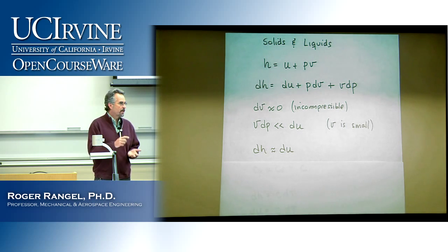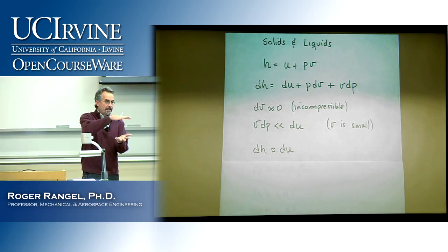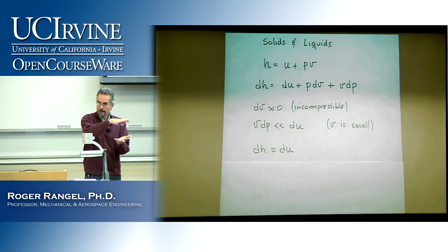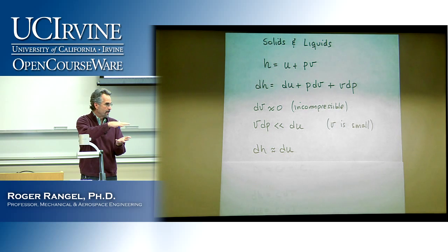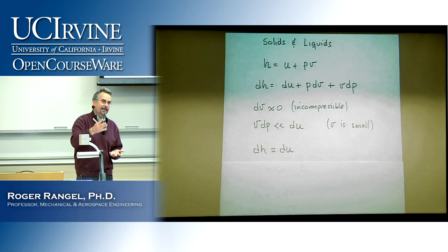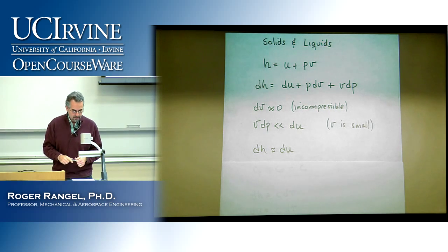That makes sense because if it is a liquid, remember, it's not turning into vapor, and I put it in the cylinder with the piston moving, and I'm just raising the temperature by 1 degree, the liquid is not going to change in volume a lot. So there is not going to be any significant work. The only reason there is a big amount of work is if the piston happens to move a lot, which will likely occur if we have vapor.